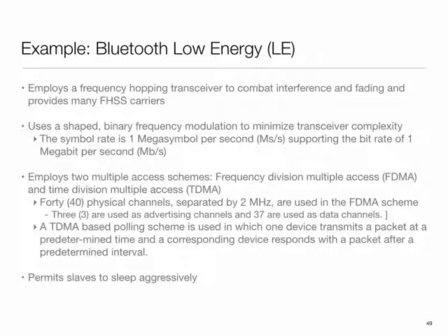They're all using BTLE because what these tags do is they transmit, hello, I'm here, every few seconds. Or like iBeacons from Apple, same thing. They last for months and years basically, because all they're doing is transmitting at a relatively low duty cycle, once a second, once every few seconds, on a coin cell. They can last forever. So that's probably the latest of the low energy standards which are there, and I'm sure things will keep coming. Okay, but at this stage, these things represent the state of affairs.